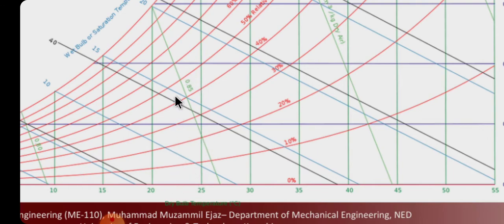Even for 23, we have to decrease the temperature to around 12 degrees centigrade, then again reheat to 23 degrees centigrade. And in many pharmaceutical companies, we have reheaters that heat the air and give a measurable quantity of relative humidity air.